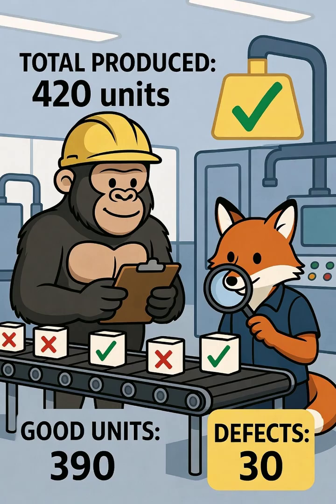Now here's a critical point. Quality is measured at the end of the process, but quality problems often start much earlier. Maybe the raw material was slightly off spec. Maybe the machine calibration drifted during the day. Maybe an operator made a setup mistake on hour 2, and you didn't catch it until hour 5. All of that shows up in your quality score.